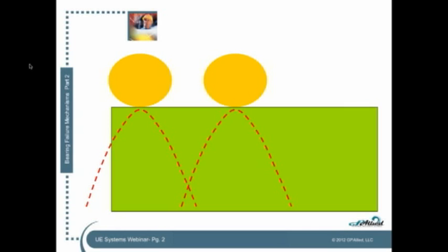Now, for an inner race, let's say we had an inner race fault, a function of fatigue, or perhaps a function of contaminants that have gotten into the bearing, and the contaminants have damaged the inner or outer race, or in this case the inner race. What we know from the geometry of the bearing, and I'll explain how we know in just a second, is that 8.193 balls or rollers will pass a given spot, any given spot, on the inner race during one revolution of the shaft.